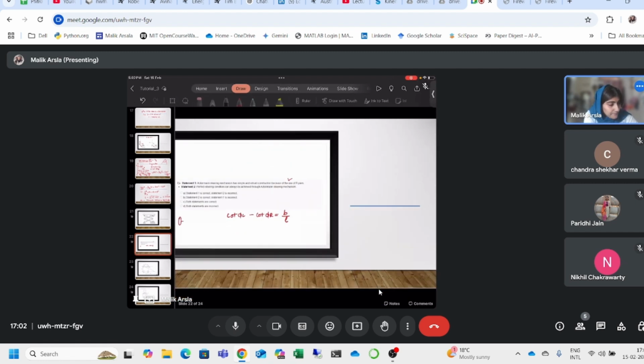So we know that if this is our vehicle and this is our steering mechanism, all of these wheels will continuously rotate about a particular instantaneous center of rotation, and when it happens then there is no slip condition and we say that this is a perfect steering condition. So these axes pass through the centers of the wheels, and this angle here is phi L, right, and this angle here is phi R.